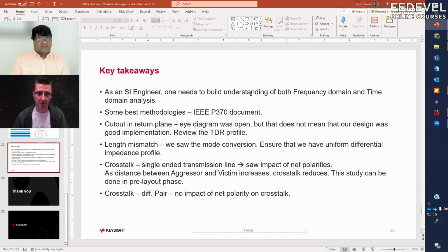That's why we would like to also see the frequency domain or frequency characteristic of this PCB, for example, because then we can very nicely see that for specific frequencies there can be problems because there will be a drop. And if our signals are running at these frequencies, then it may be wrong. That's why it's important to see time domain and also the frequency domain.